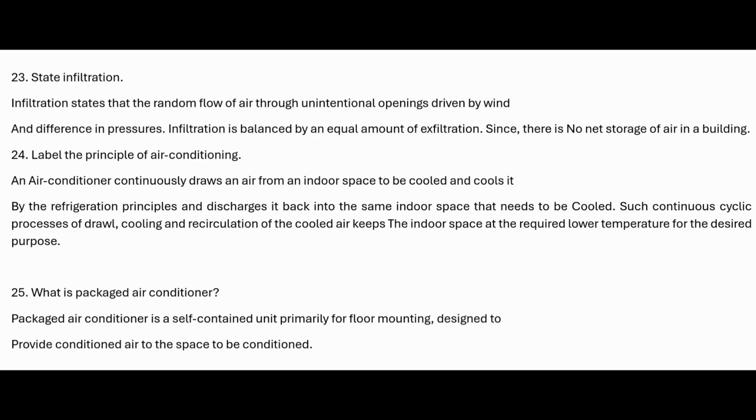State infiltration. Infiltration is the random flow of air through unintentional openings driven by wind and the difference in pressure. Infiltration is balanced by an equal amount of exfiltration, since there is no net storage of air in a building.